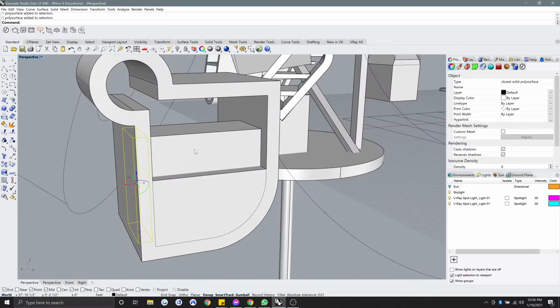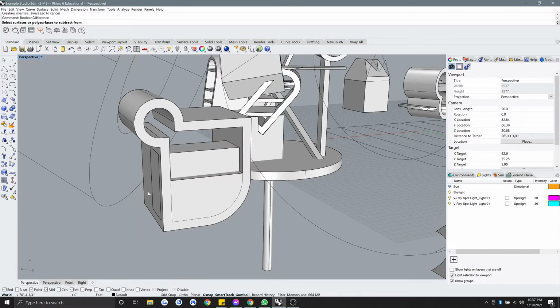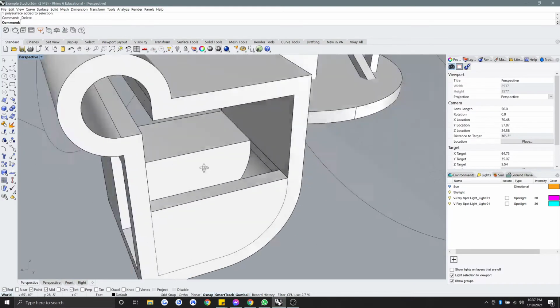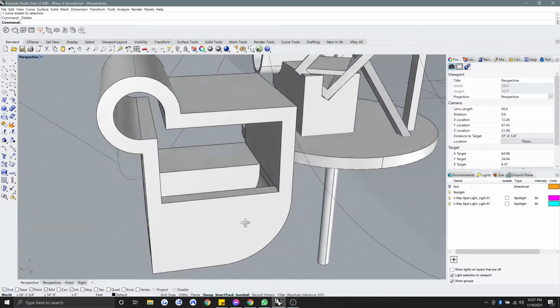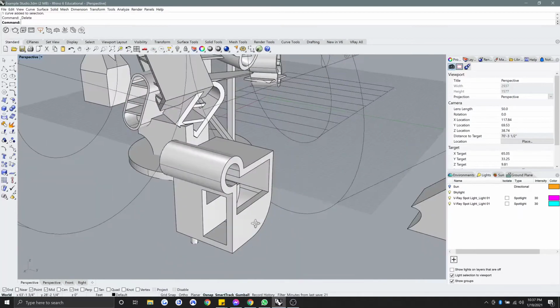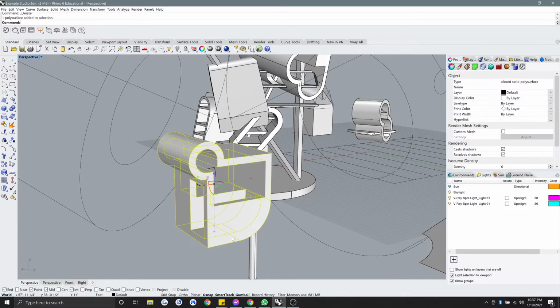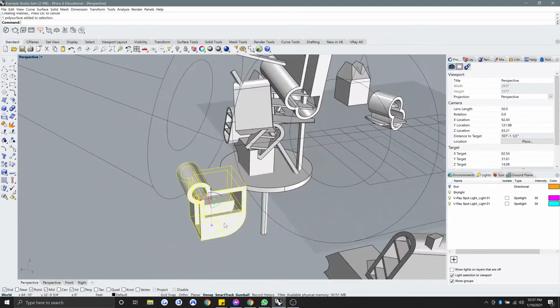And because I want that bit to be cut out, I'll just rejoin these two, Boolean unioning them, and then I'll Boolean difference from this larger shape, this one. And that's going to leave me with an interior that is substantially kind of more complex or dynamic or specific than just one simple extrusion. I'll click on this, merge all faces, just to keep the lines as clean as possible.